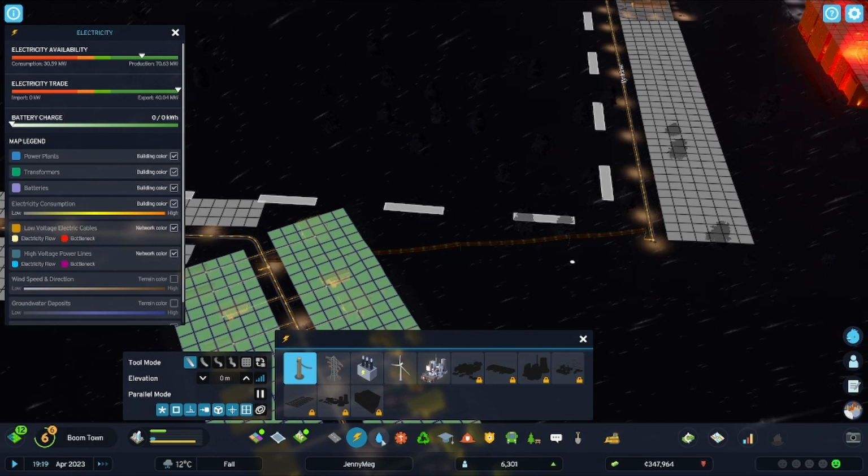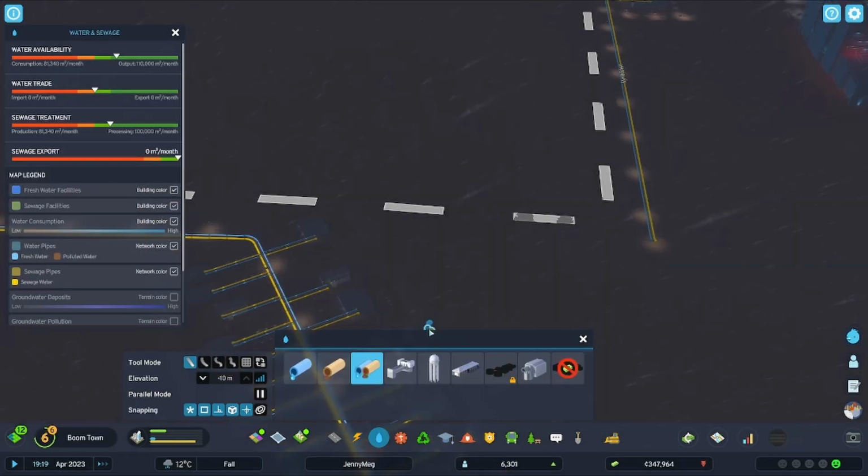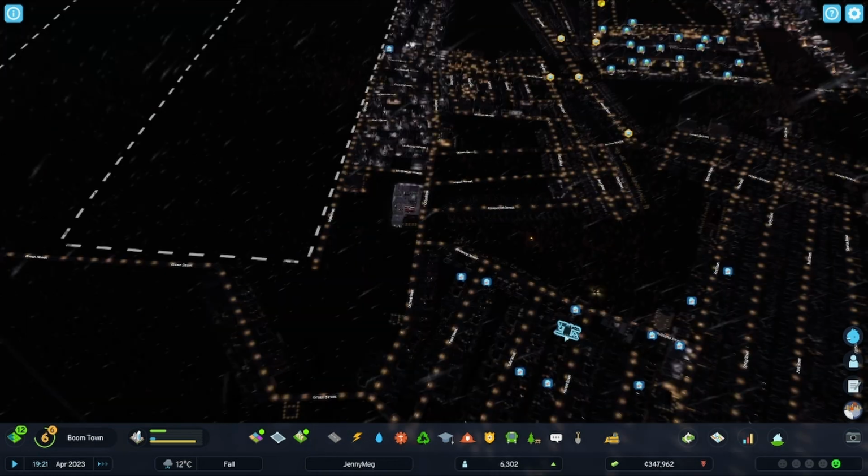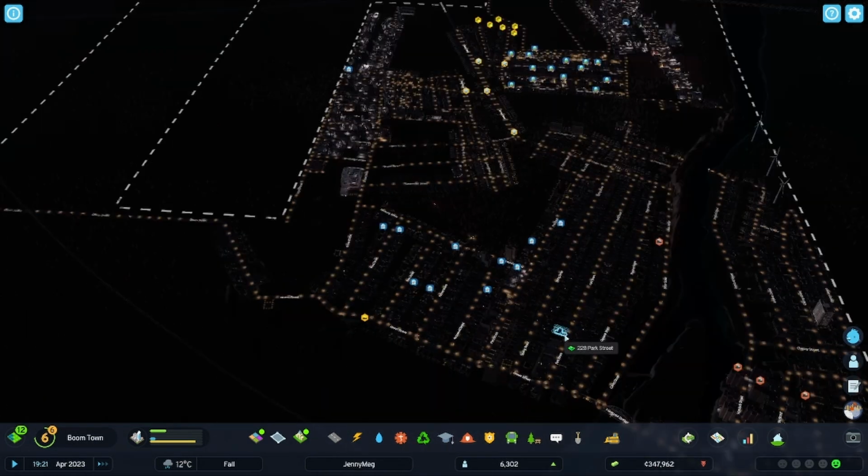And the same thing with the water tool, with the water piping. It does the same thing. It's a little bit off. You've got to go by that white line right there, and where it kind of links, and it puts a little circle right where it looks like it might be connecting. So you really have to pay attention to that, because you can mess up your connections really quickly. That I kind of wish they'd fix.